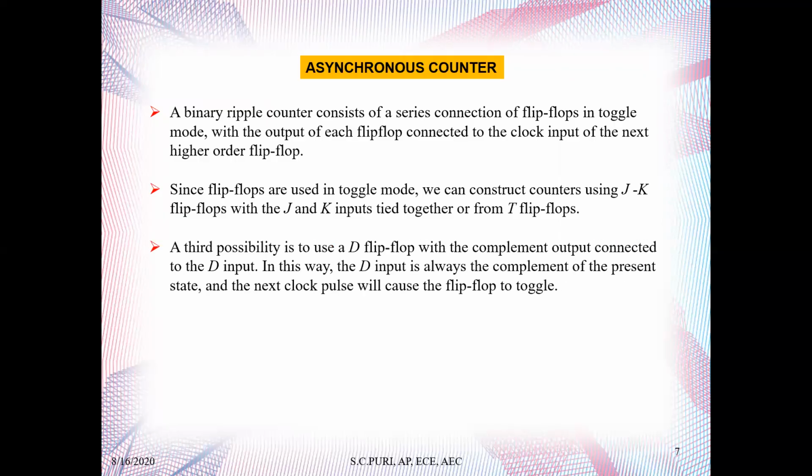Another possibility is to use a D flip-flop with the complement output connected to the D input. In this way, the D input is always the complement of the present state, and the next clock pulse will cause the flip-flop to toggle. So it's not that you cannot use a D flip-flop. You have to use a D flip-flop in a specific configuration.